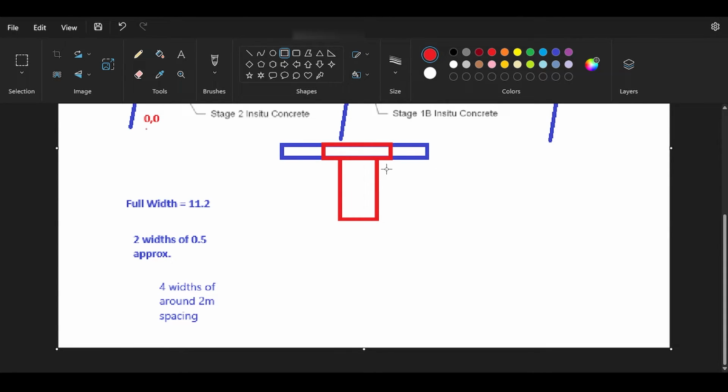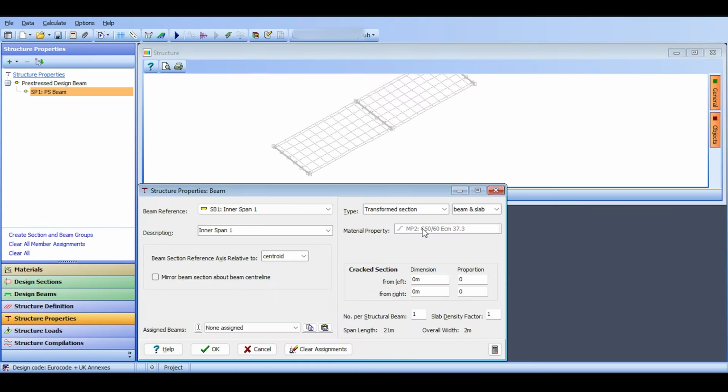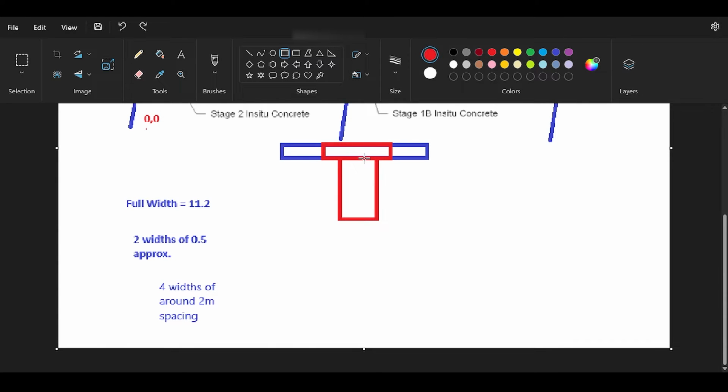You can, and a fun fact here is, if the slab and the beam have the same material, then the transformed section and the gross section are going to be the same, because in the transformed section, nothing will change. Here, you have a cracked section, and by cracked section, I mean, now look, this is our section, right? We have a slab and we have a beam.